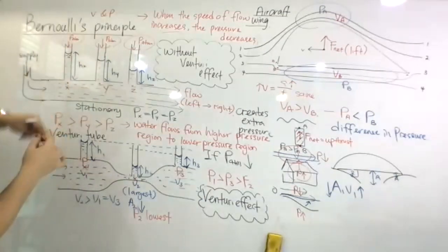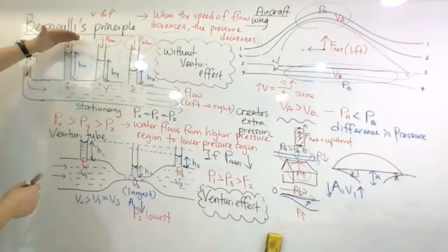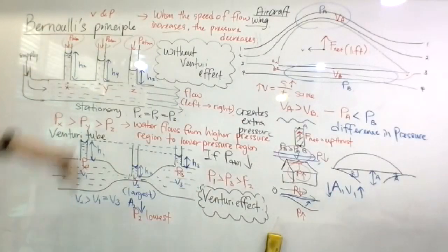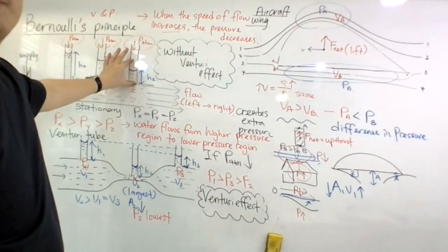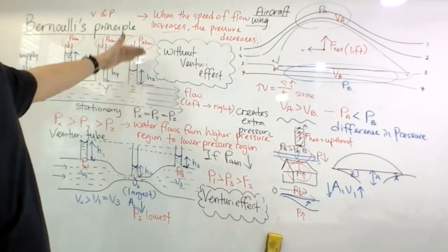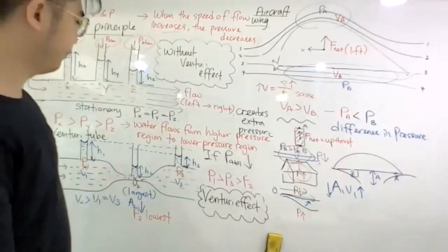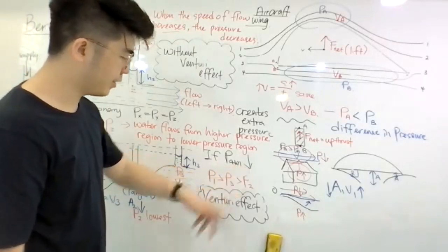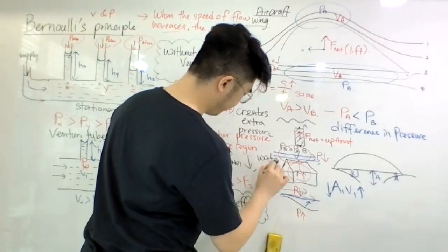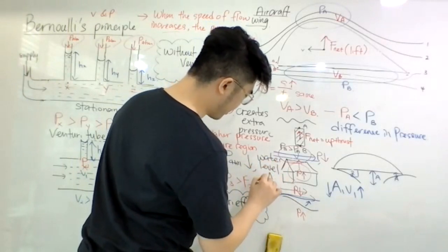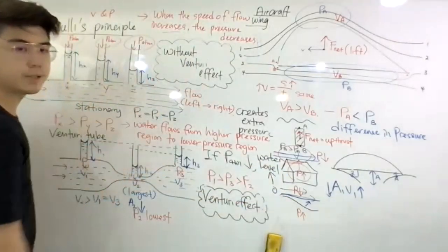Logically, you can think if this one, which is preventing the water from coming up, decreases, then the water will rise higher, right? If the atmospheric pressure decreases, then this water will rise higher, even though the pressure here does not change, because the amount of force pressing it decreases. So this one will go up. So if atmospheric pressure decreases, then what happened? Water level increases. All of them, all together, will increase.